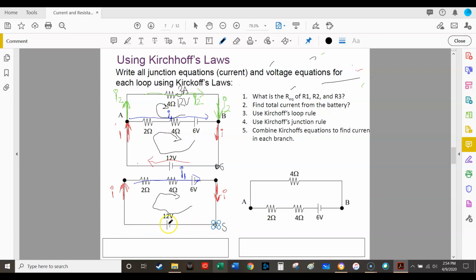And we're going to walk to the left, and this battery is pointed to the left. The positive terminal is on the left, the negative terminal is on the right. So that battery is pointed to the left in the same direction that we're pointed. So that's going to be 12 volts, right? I'm going to leave a little bit of space between that and the equal sign because I do have another battery that I have to work with. Okay? So now I'm going to be walking up.